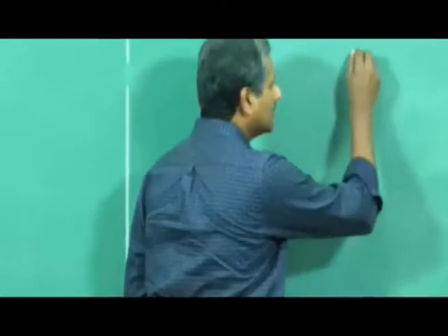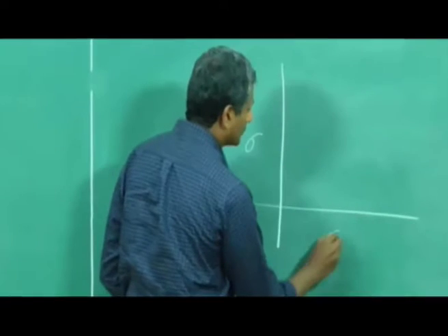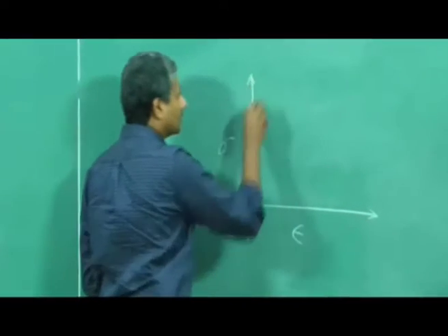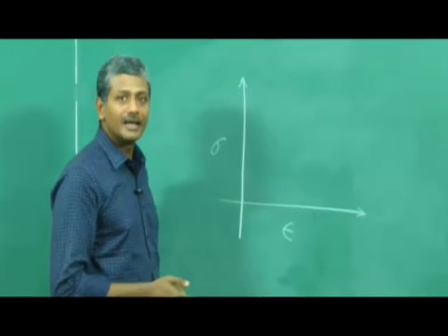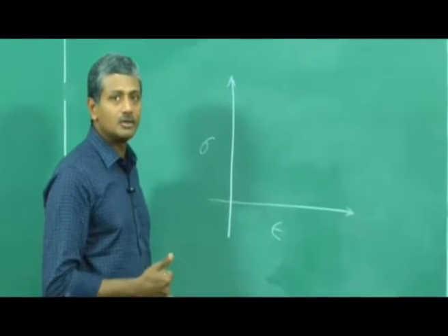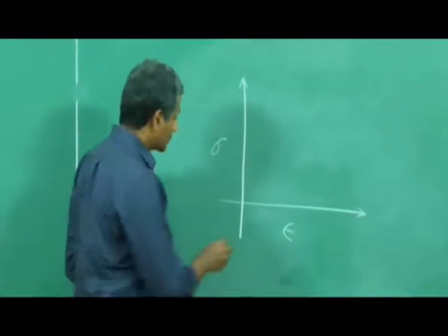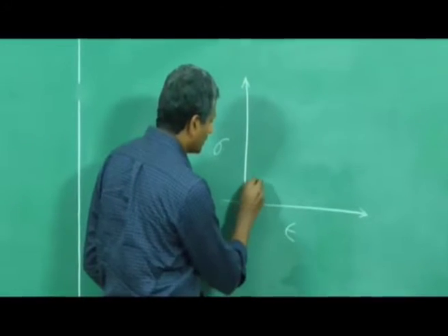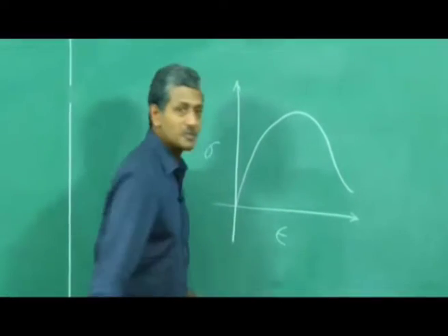If you remember, we talked about the fact that the stress-strain diagram of concrete is linear to begin with, but then it soon becomes non-linear, and I said that non-linearity is generally introduced because of the interfacial transition zone in the concrete. So you have some linearity to begin with, but soon your concrete starts behaving non-linearly.